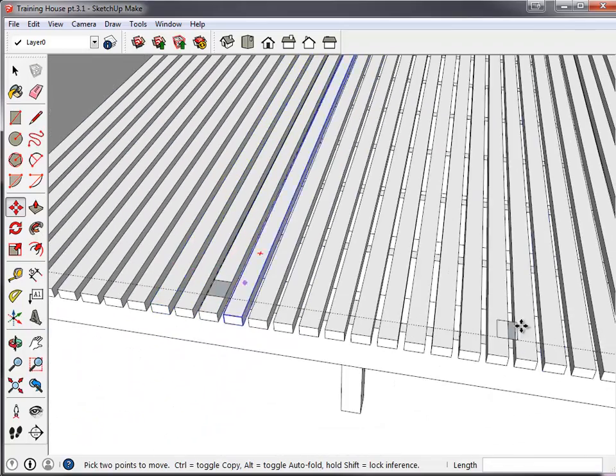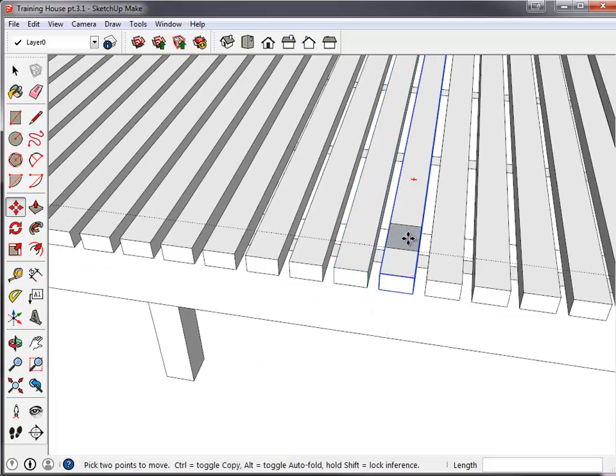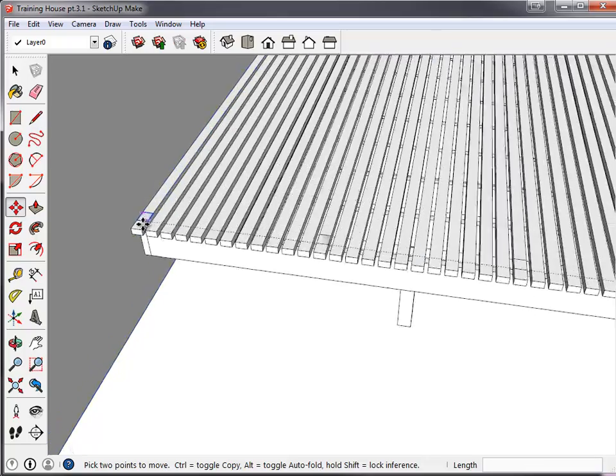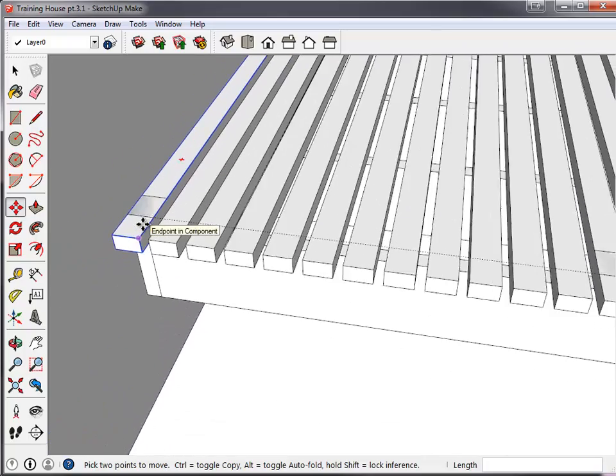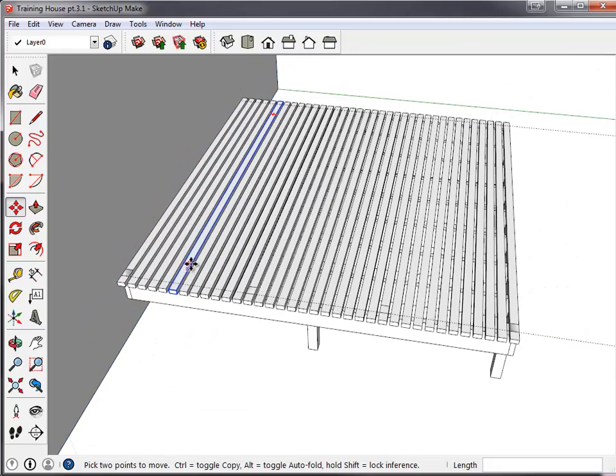You should only have to do this for the first 2. If your deck boards are off or your square is incorrect, change your square size to fit whatever size you made the deck board. Don't go back and actually change the deck board itself. Just make a square that fits to the size of your deck board that is 3 inches wide.